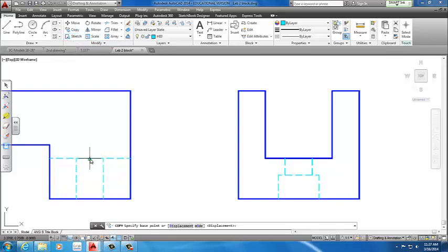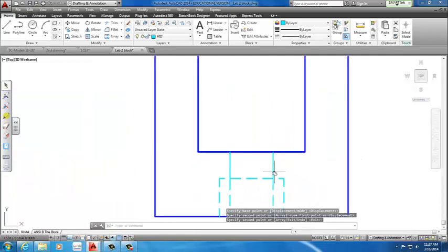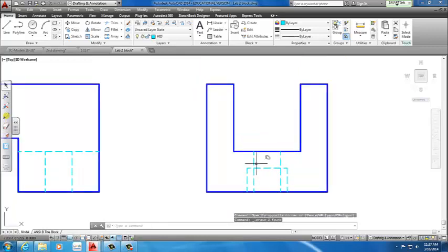I'm going to copy and stretch this from midpoint down to midpoint because it's too big, because I want to place it in the viewport. In doing so, I double layered it, so that's why this viewport is not shown as hidden. To do that, I can just stretch that down, delete those two lines I don't need. And that gives me the correct design, even though the previous one only shows a single active viewport.